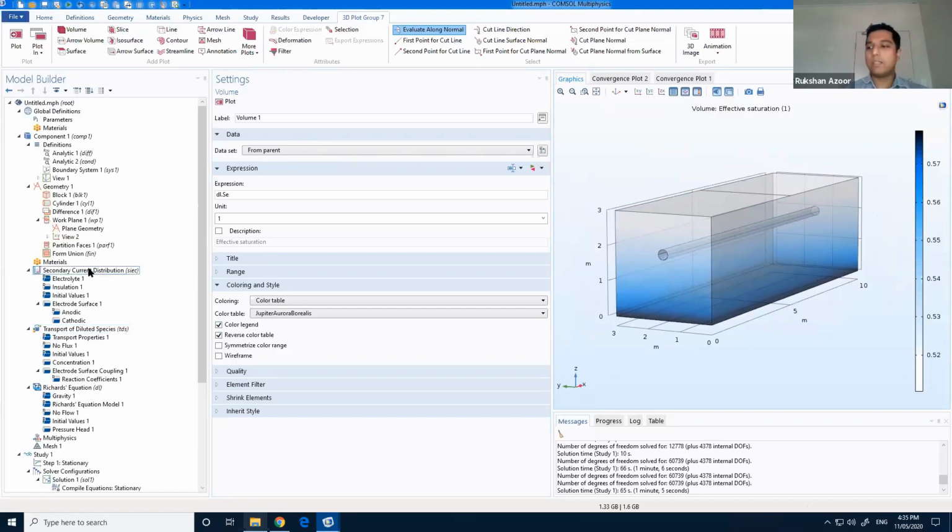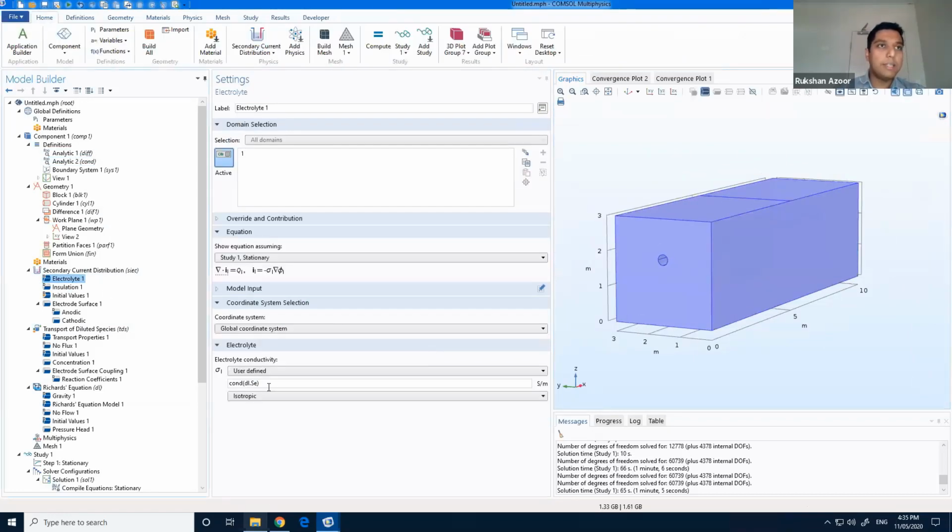but before I move on to the other examples, some general comments on things that I have missed, maybe. Important things in COMSOL, in all these fields, you can write any equation you want. You can have any variable you want. If there's a variable that corresponds to another physics, it will solve it and use that in the equation. It will do a complete coupled solution for you.